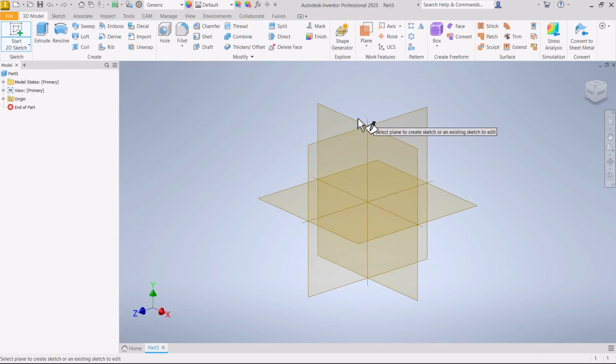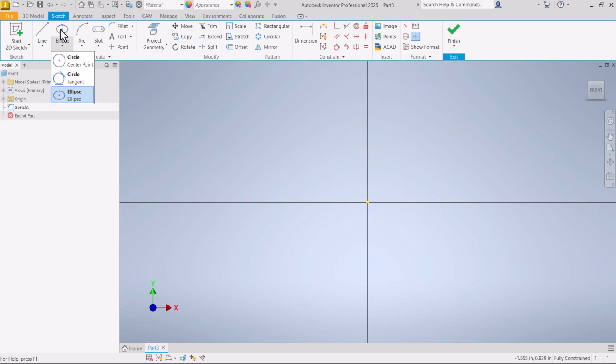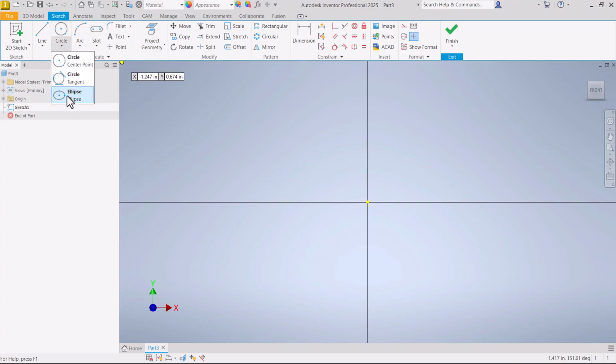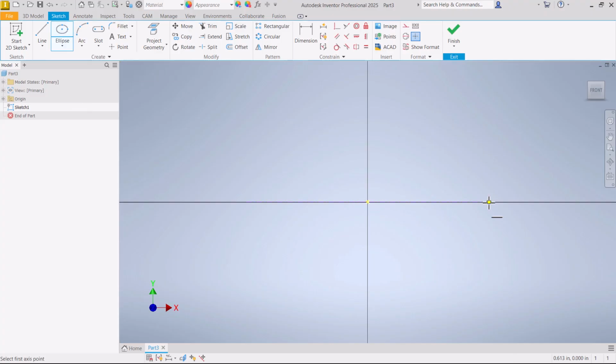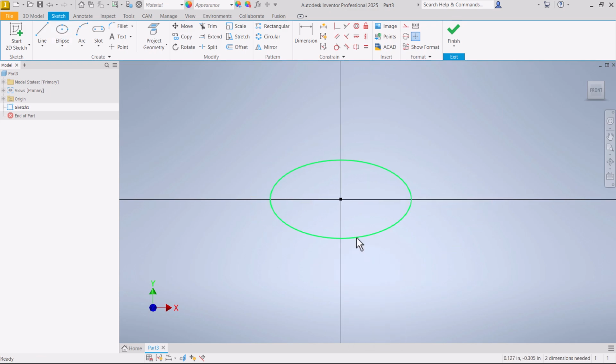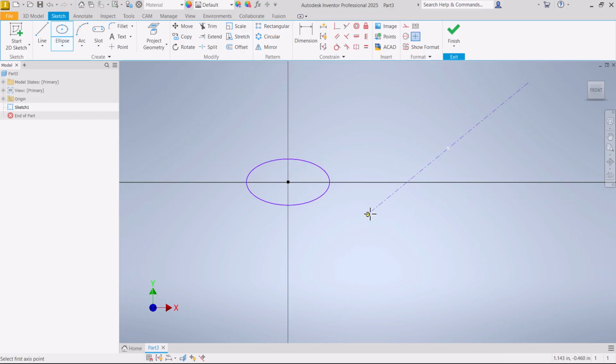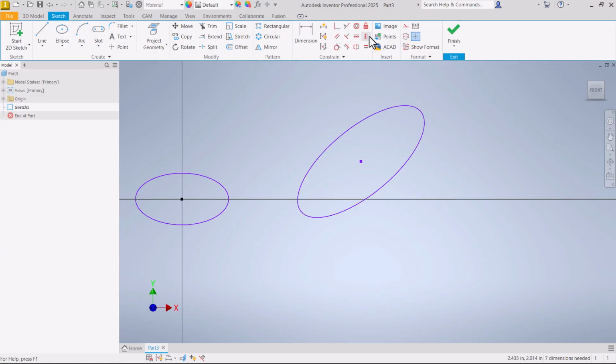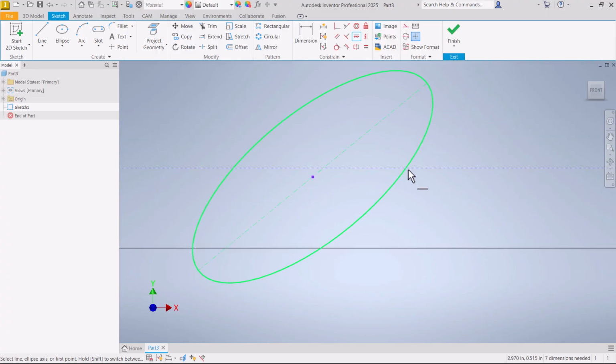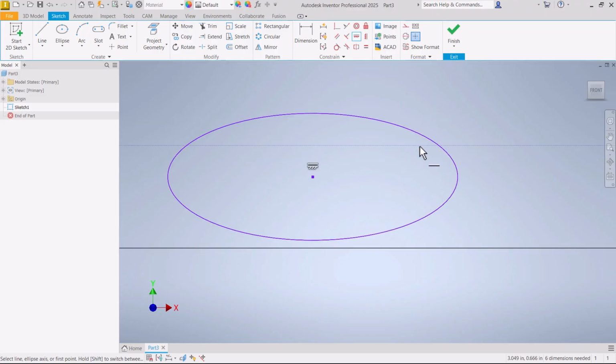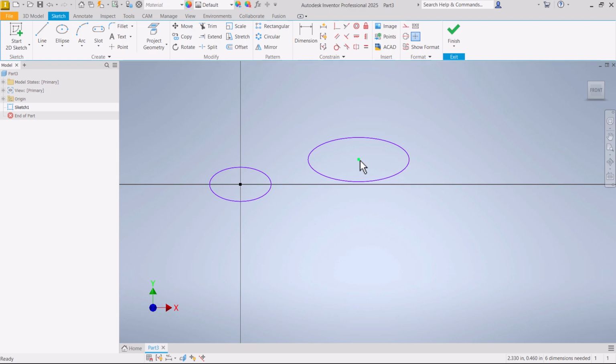Let's get rid of that sketch, start fresh, create an ellipse. That is down under the circle command. You can draw an ellipse. If I start out horizontal, see it's snapping to horizontal there. So that gets me lined up. There is that horizontal constraint on that axis. But if you draw your ellipse at an angle, you can apply horizontal or vertical. Let's click the horizontal constraint, and as I get down close to this ellipse, you can see the axis highlights. That gets the long axis of this ellipse. Tell it to be horizontal, so that gets it lined up.